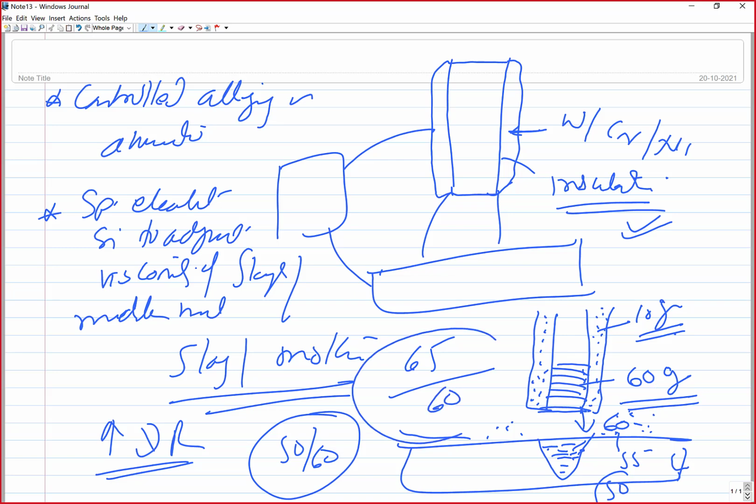So the deposition efficiency is greater than 100%. Powders of the required metal are added in the coating so that they also melt, just to increase the deposition rate. It is just about the way we calculate. I think that's all about these coatings and their roles.